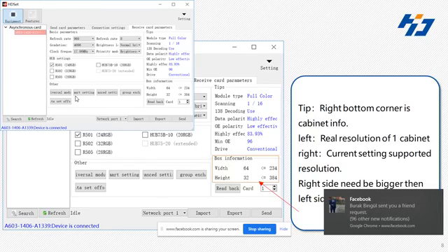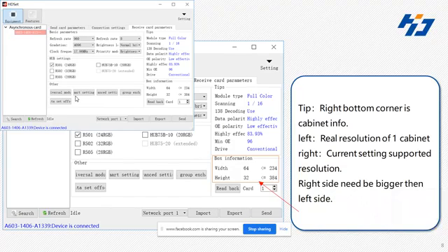As you all can see on the screen, there's a software called SDSet. So when this software will appear, for this software you need to click on settings, and in setting you have hardware setting. When you will click on hardware setting, in the left hand side corner of your screen you can see your control card will be available there. First you click on that control card, this screen will come where it will show send card parameters, connection setting and receive card parameters. As I have already discussed,